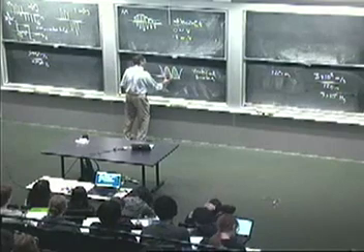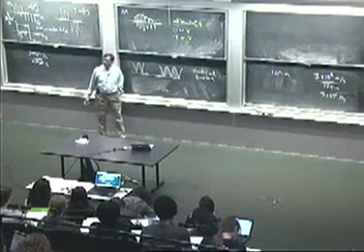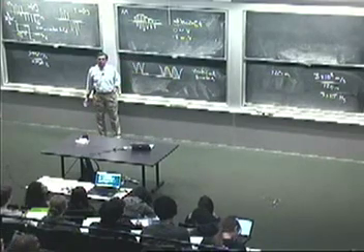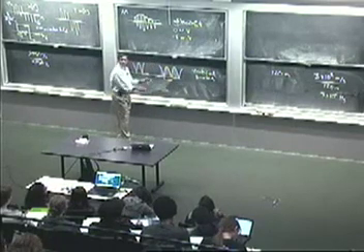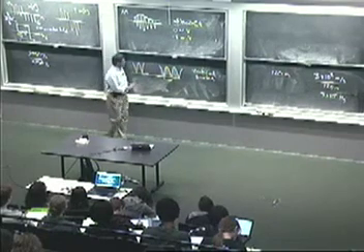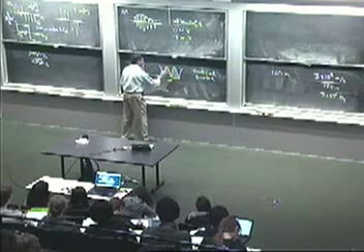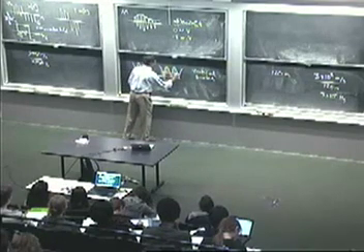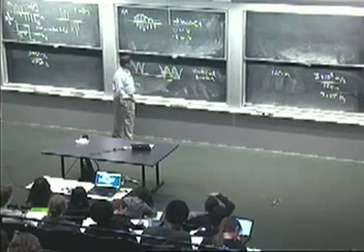Is there any window size that will actually give you a constant signal if you're in the body of this? I mean, if you took a window that was equal to a period here, this is periodic, right? While the sinusoid is ringing, it's periodic. So if you took a window of this size and then slid it along, at least in the body of this, you're going to get a constant because you're picking up the average value of the rectified sinusoid.